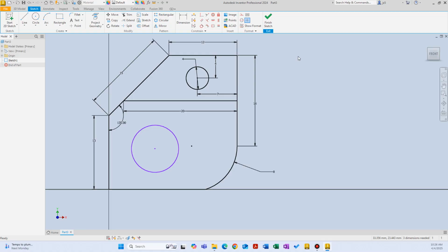And we covered the constraints before, so if you would like to apply a diameter to this circle, you can by using general dimensions, but also you can select the circle and hold the Control key on your keyboard and select the other circle and hit equal. Now the diameters are going to be equal. But if you don't want to do that, you can undo and you can just general dimension and click on a circle and assign a different diameter.